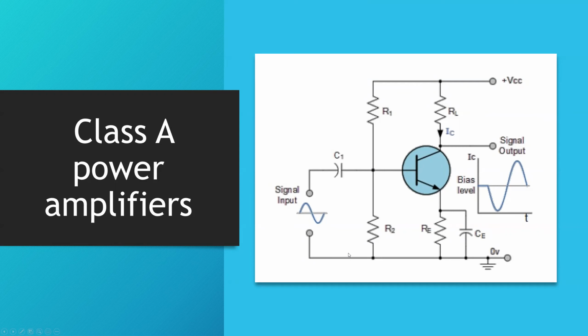Now, what are these resistors for? These resistors are used for voltage biasing, since we need a specific amount of voltage to be at this node for this device to operate in the active region, which is about 0.7 volts. And these resistors are used to achieve that.